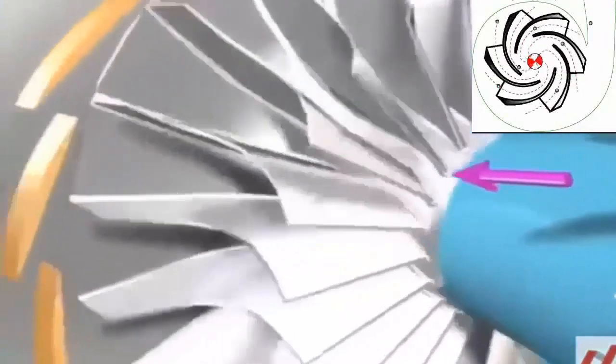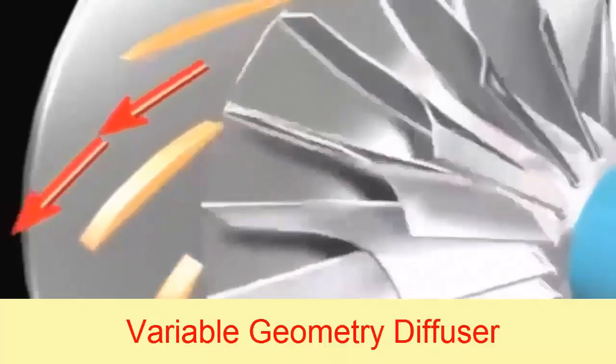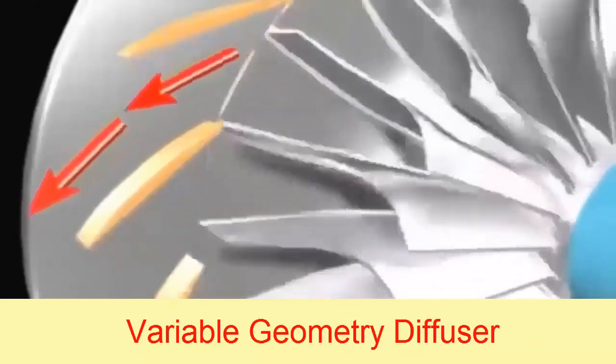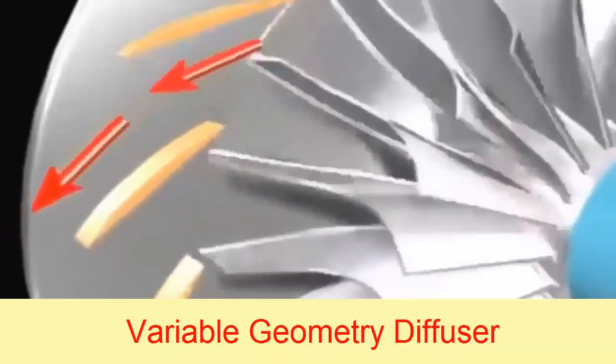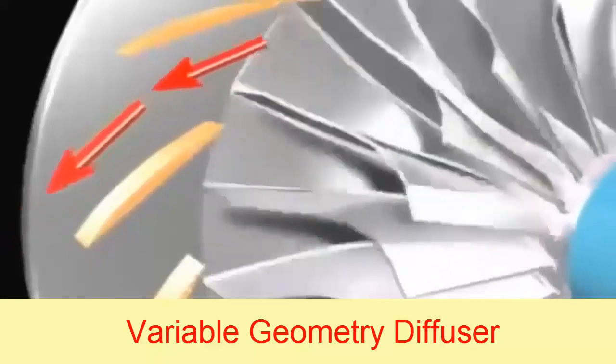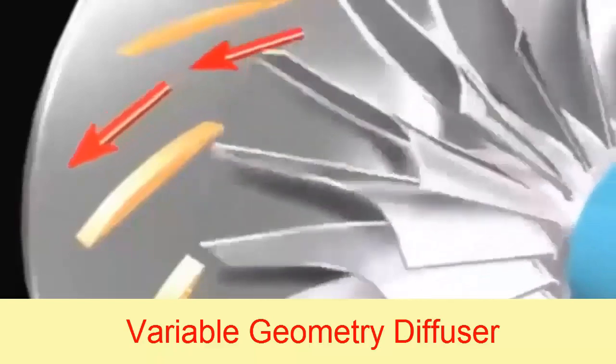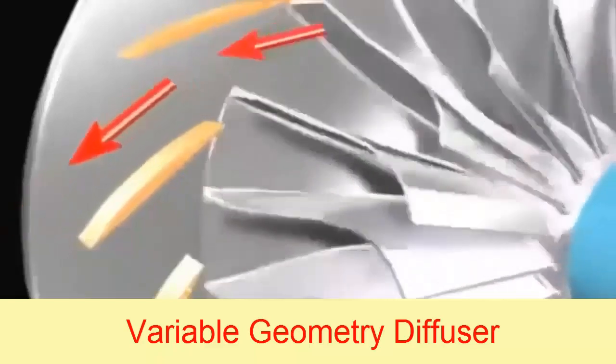If we see the animation, we are getting closer, we are at the impellers and we see that we are going to go out and mount this diffuser that we have at the exit. The geometry of the diffuser has to change to also adapt to the amount of refrigerant that is entering. If less is entering we cannot have the same area as if a greater quantity is entering, so we are going to have a throttling or a variation in the geometry of the diffuser at the outlet of the compressor, at the outlet of the impellers. This area will then allow us to achieve the pressure that is needed.